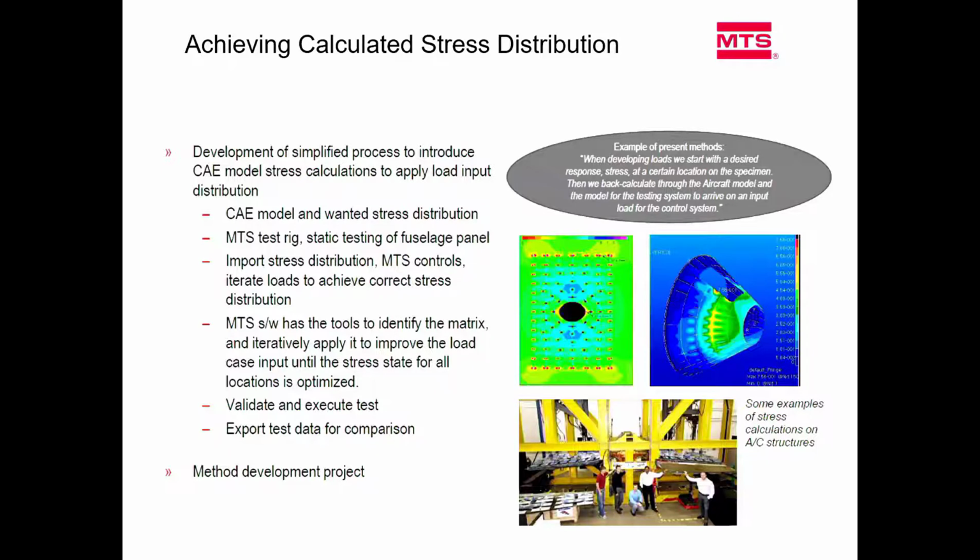For example, in this aero testing example, the customers have this kind of test system, but they want to achieve some measured strains at certain locations, and we want to create a method so that using actuators, we can achieve the measured strains.